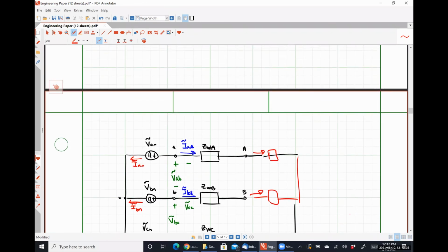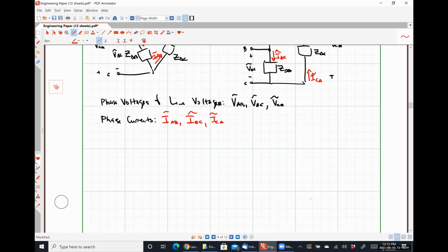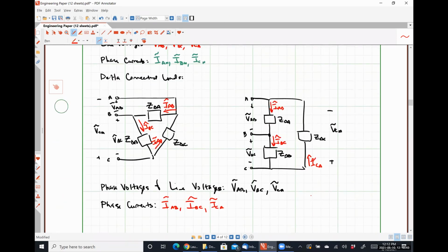No, but I would say the delta connection is the one where they look like they're in series, but they're never in parallel either. They're never all in series and they're never all in parallel. For them to be in parallel, they would have to share both sets of terminals, and that literally never happens, because if all three voltages were in parallel, they better all have the exact same voltage, or else you have a short circuit somewhere that's going to start a fire, right?